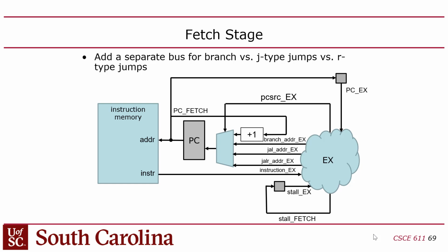You've got to make sure that there's a one cycle delay between the output and the input. Otherwise, what will happen is the control unit will say, I've got a branch, stall. And as soon as it says that, combinationally, that stall signal will convert the incoming instruction to a no-op. And then the control unit will say, oh, look, it's a no-op. We don't need to stall. And then it'll set the stall to 0, which will convert the instruction back to the branch. And then it'll say, oh, it's a branch, I have to stall.